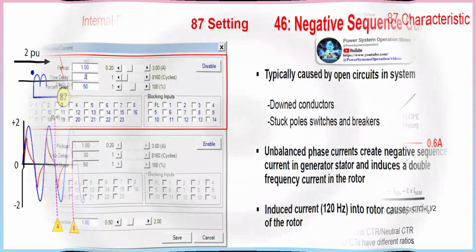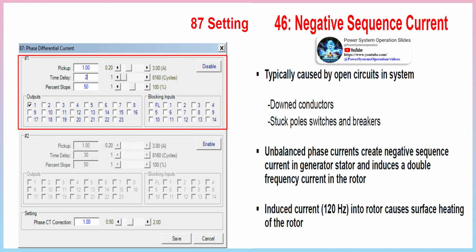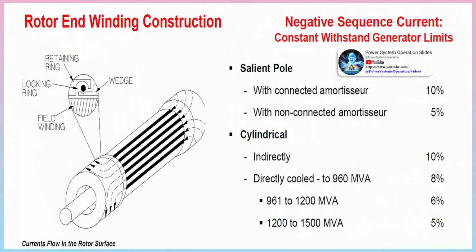Stator phase faults: 87G phase differential is primary for in-zone faults. What goes into the zone must come out. Challenges to differential: CT replication issues, permanent flux causing saturation, and DC offset desensitization for energizing transformers and large load pickup. It must work properly from 10 Hz to 80 Hz so it operates correctly at off-nominal frequencies from internal faults during startup, and may require multiple elements for CGT static start.